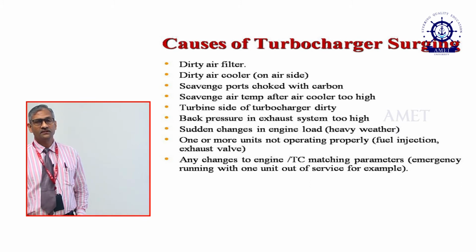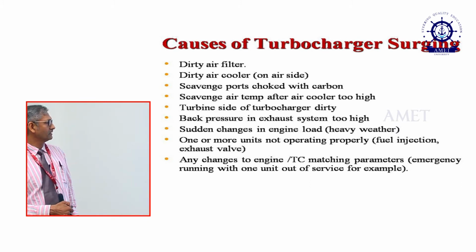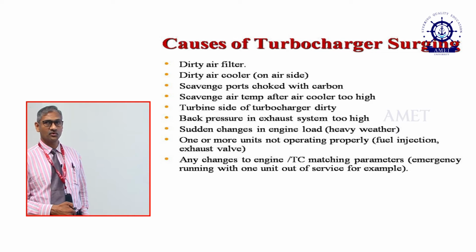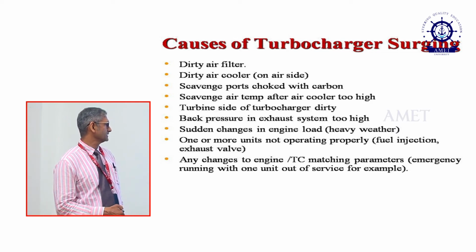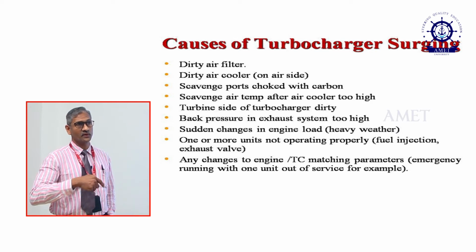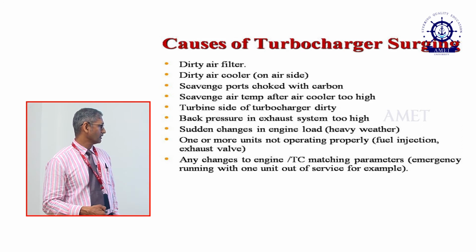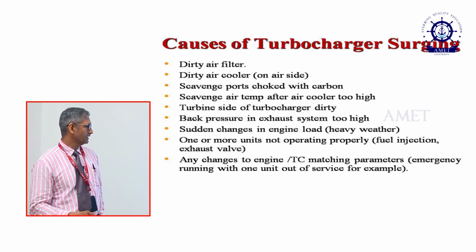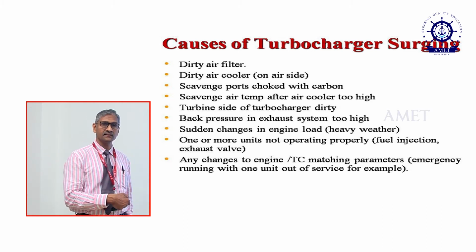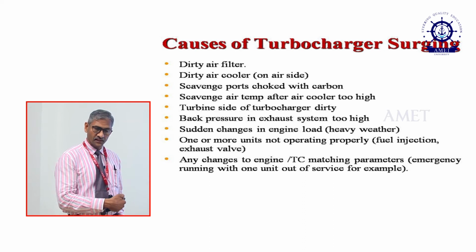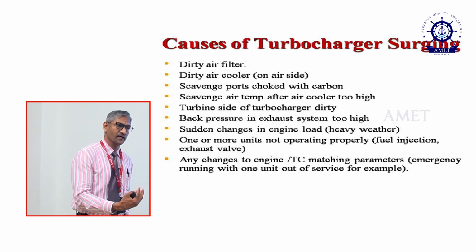So, what are the causes of turbocharger surging? It could be a dirty air intake filter, it could be a dirty cooler, or it could be that the scavenge ports are choked, or it could be that the turbine side is dirty, there is a back pressure on the exhaust gases as they go after the turbocharger, or there could be a sudden load variation on the engine, because of which the engine is unable to cope, or the fuel injection system is having a problem, or you have 2 or 3 turbochargers in the engine and one turbocharger is having difficulty, so there is a poor match between the air required by the engine and what is being supplied by the individual turbochargers.